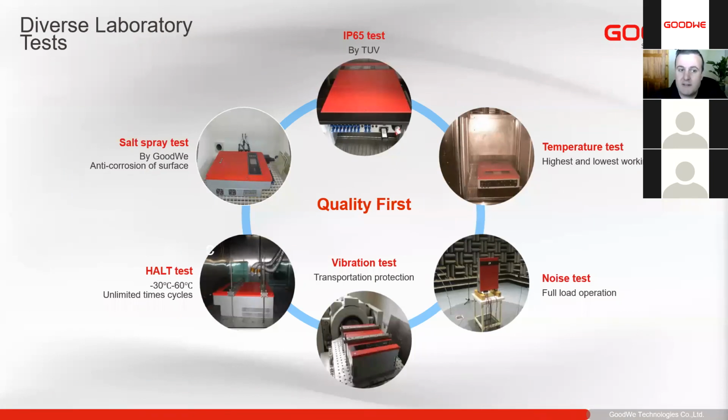All our devices go through rigorous testing before they leave our factory. Not one of our inverters comes out of the factory without rigorous testing. All go through the IP testing to make sure that no humidity can get inside, high temperature testing, noise, vibration, starting testing with cycles, and spray tests as well, to make sure that our IP rating and everything is perfect on our devices.